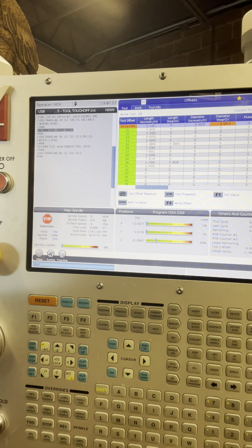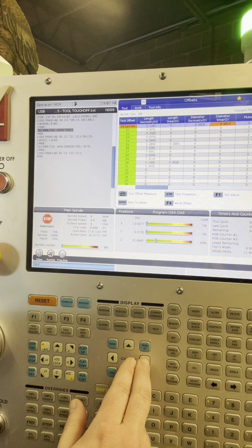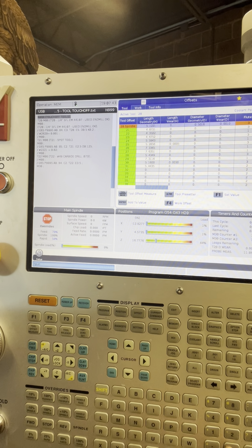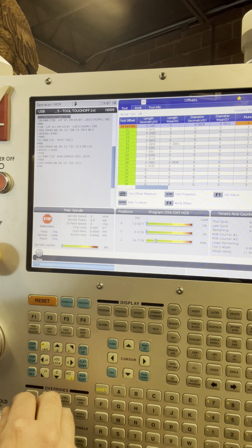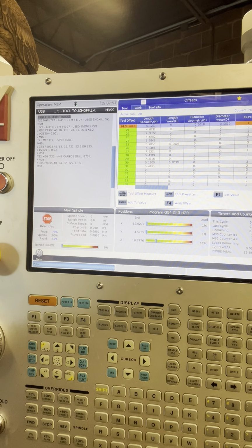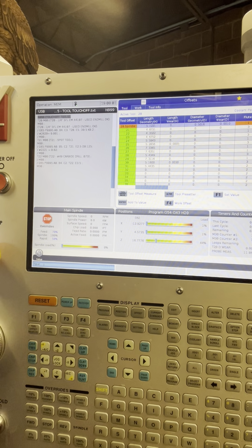Brad? Oh, you said about putting the number of flutes in too. So the number of flutes is #16. Is this a 3-fluter? Yes. It is, okay. I'm gonna reset this. I'm just gonna change this to 0. It would not let me, oh, you can't do 0. All right, do you have programmable coolant on here? No. You don't, okay. Because that's another one. So when you zero out this table, you know how you can origin and zero out everything except for the probe? Don't forget not to zero out the probe.